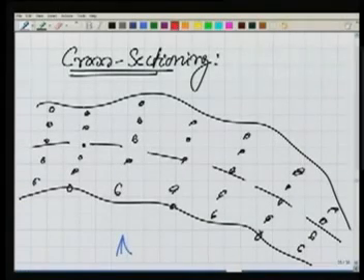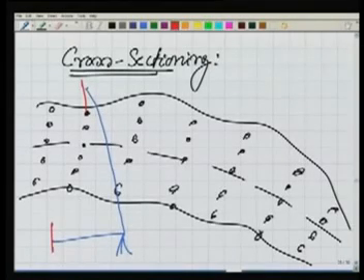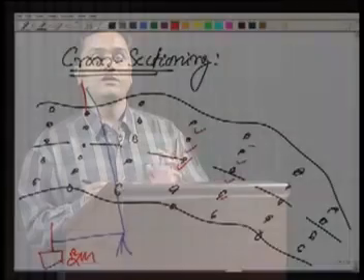So what we will do is keep my staff on each of these points and take the sight to it, while I have already taken a sight to a staff kept at a benchmark. Using this, I can determine the RL of all these points. So by this method, we have a carpet of points. It's not only a single line along which we know the points, but a carpet of points covering a wide area.